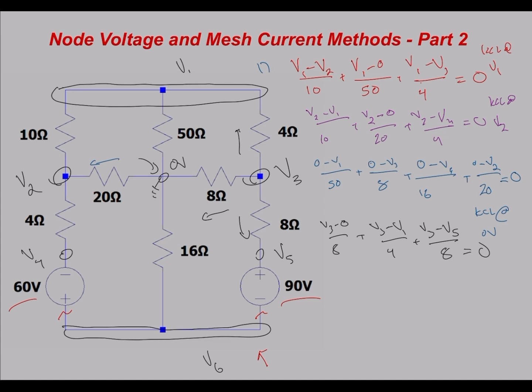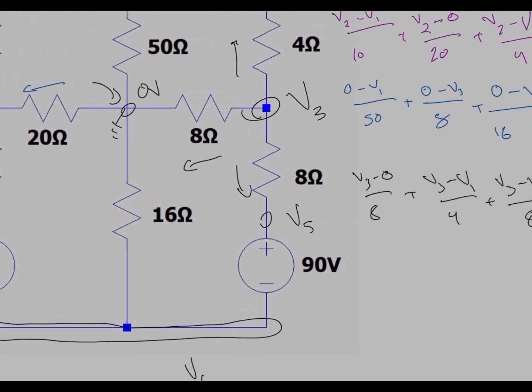So what we have to do here, these branches with these voltage sources, these are called supernodes. And supernodes occur when you have an independent voltage source that's connected to two non-reference nodes. So we can't form a KCL equation using our normal methods, but fortunately, with a bit of critical thinking, we can see that these nodes, we can actually create a relation between these two nodes, which will allow us to get two equations. And here we can see that if we want to relate for this branch these two nodes, we can actually convey the information we need.